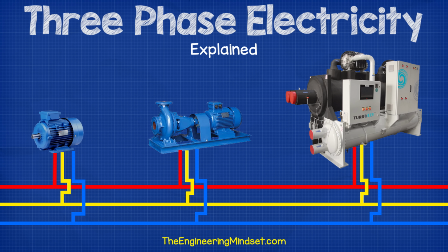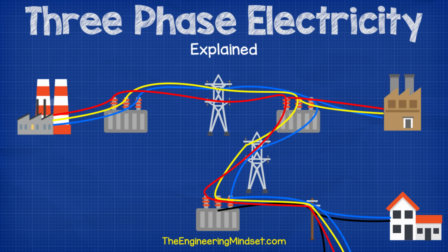A more practical application is to power electrical induction motors and other commercial and industrial equipment, as 3-phase will provide a lot more power to these items, meaning you can pump water higher or you can run motors faster, etc, etc. Power is generally generated and distributed in 3-phase, and transformers are used to change the voltage.